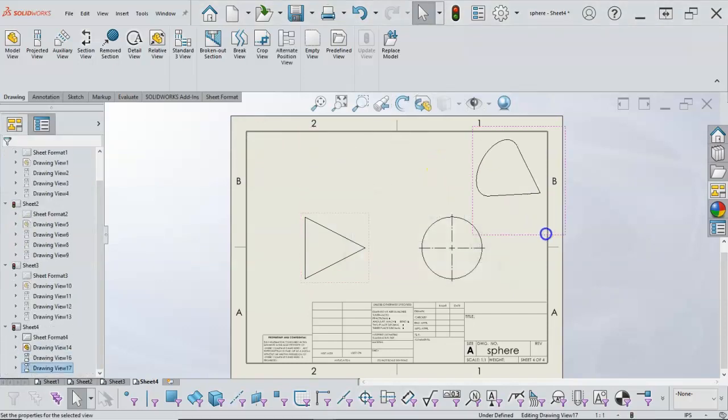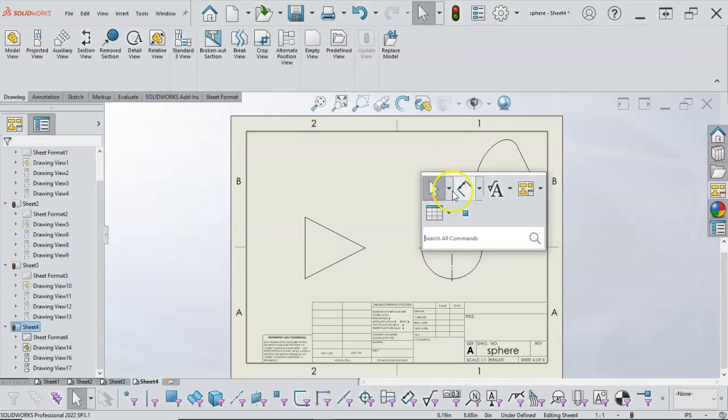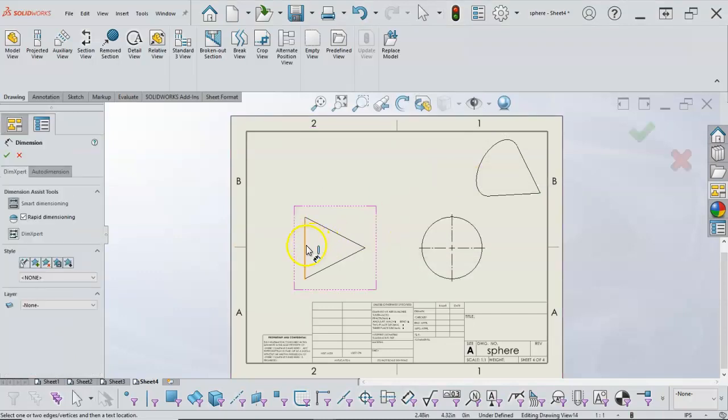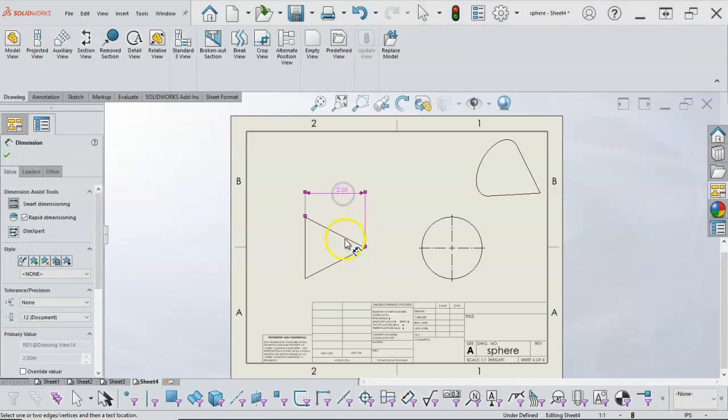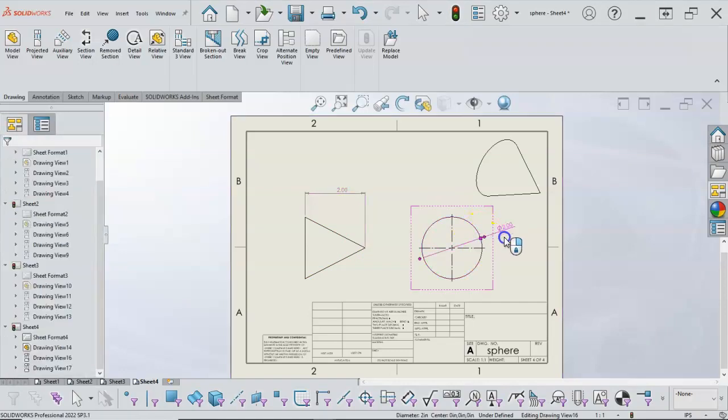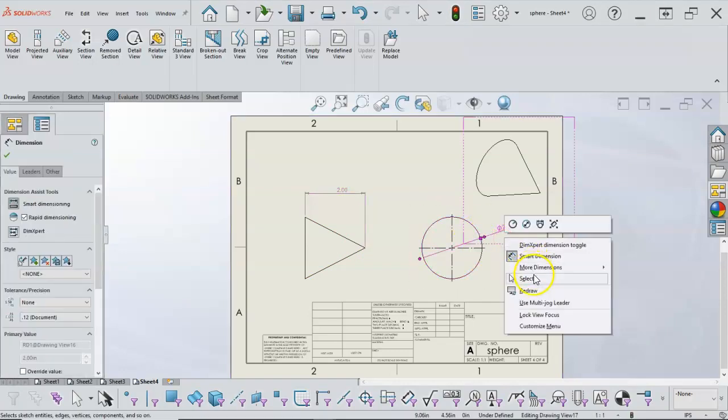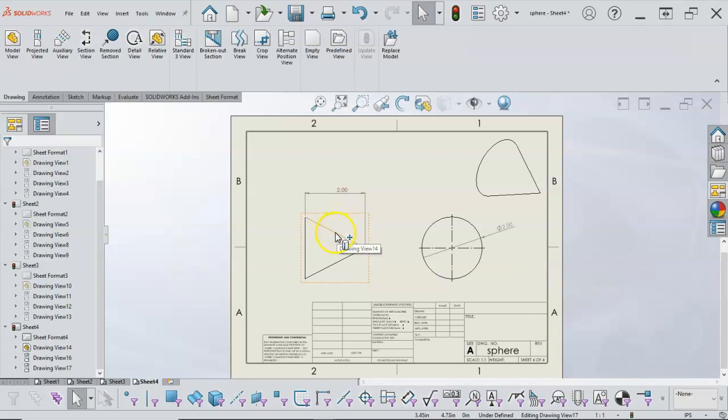And we have those. So when I go to dimension this, slipping into the S key, we can go to the vertex. That little cylinder with the line was a silhouette edge, which can be handy. We're not ready for it just yet, but as we drag along that edge, it's basically saying the line that is generated by the plane passing through that shape gives us something that we can relate to.